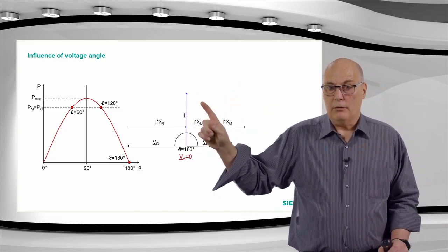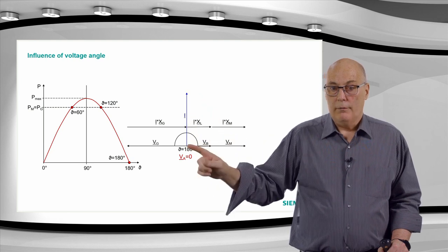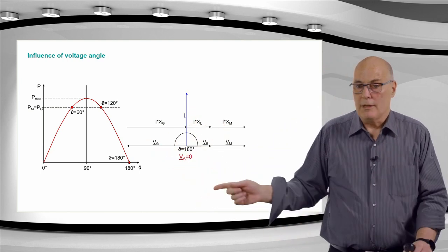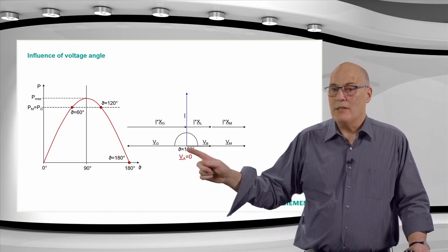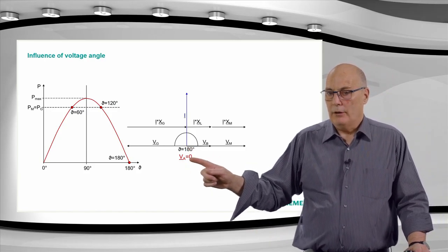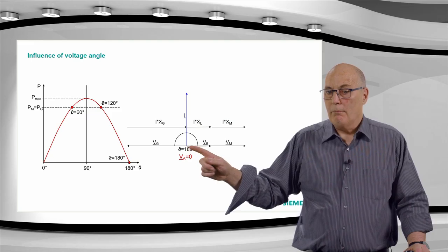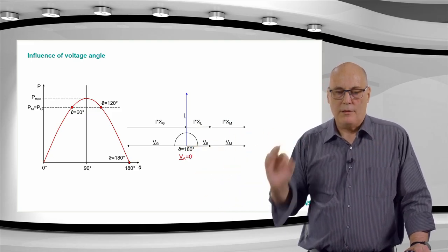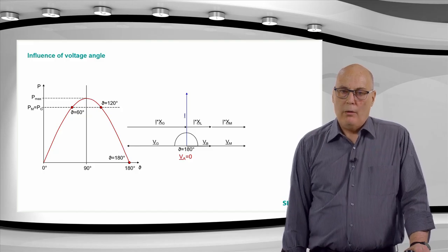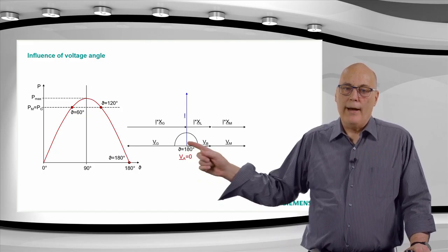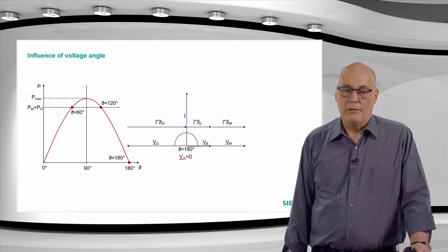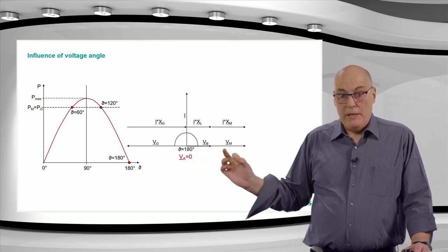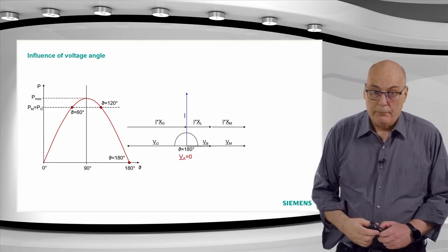You can see the current is really large, the load current. During the point, the load current has increased a lot because we need a big drop between the left and right side, but the power transferred is 0 at the relay location because power is I times V times cosine phi, and cosine of 90 is 0. There's no real power being transferred, only reactive power, VARs. No watts, only VARs at the relay. But the impedance is 0, which is a problem.